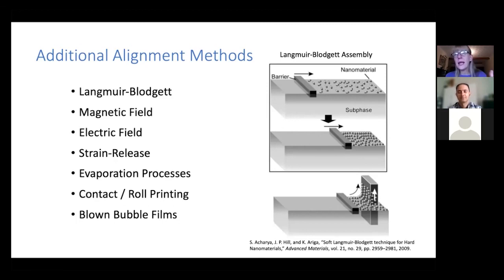But with this sort of process, you really want pretty good constraints on the diameter. If you have a wide range, then you're going to have less and less concentricity, because different diameter rods are going to cause movement of that rod inside the fiber relative to the tube. So you want something pretty monodispersed with regard to the diameter.